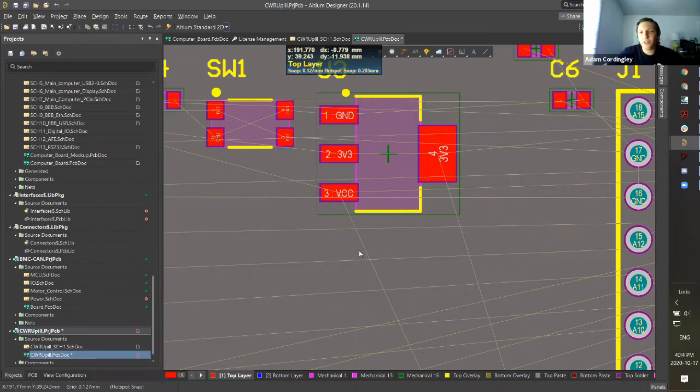So that's my diatribe on the auto router. I just think you also learn things about your design. You learn how to think about electrical design and how the board's going to go together when you do it yourself. And furthermore, I think the argument of time saving doesn't hold: the auto router saves you almost no time, because you've already spent all this time making a nice schematic.